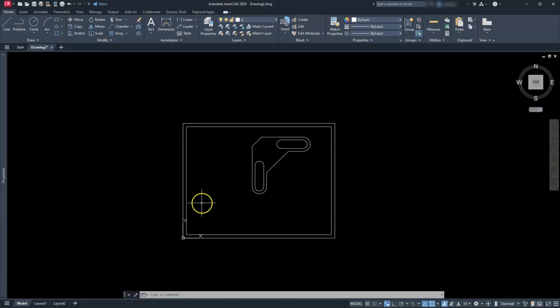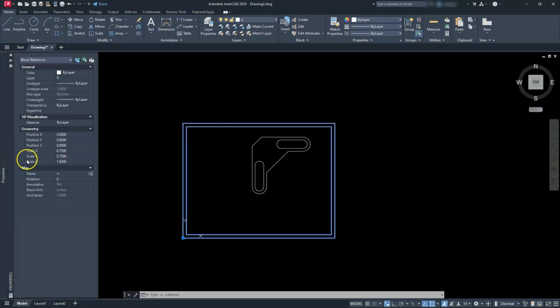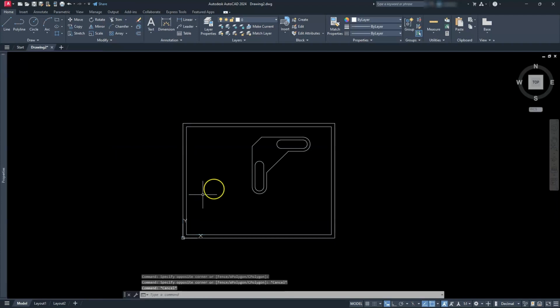Now, you've seen that, and I hit the escape button a little too quick for you. You see that I also left the Z scale set to 1. We're creating 2D drawings, so that's actually irrelevant. You don't need to worry about a Z axis because we created this as a 2D title block. So you can put a number there, or you can just leave it at what it is. All right, next, let's go ahead and move this down and get it better into position.